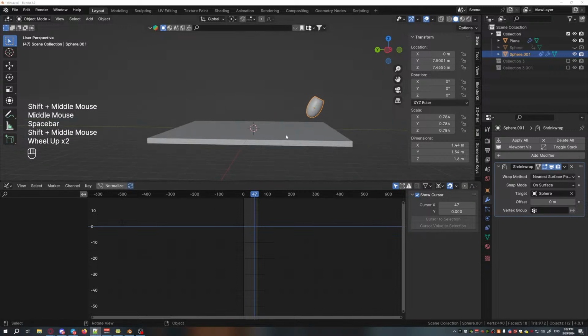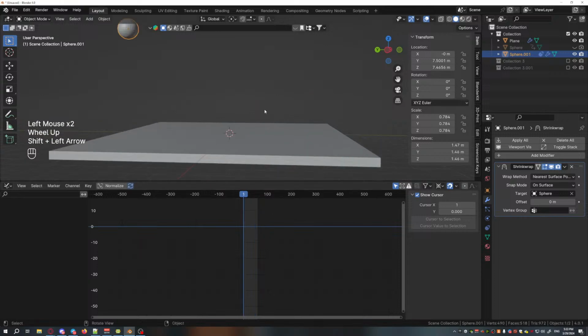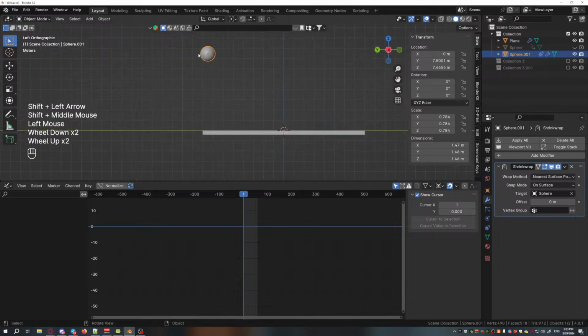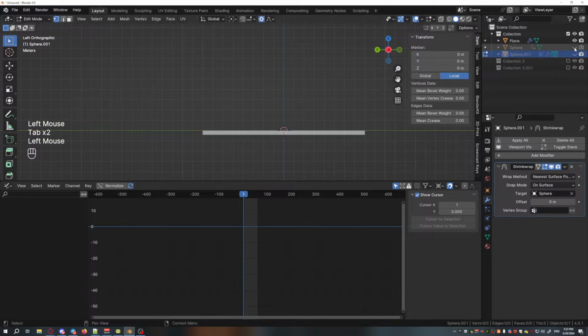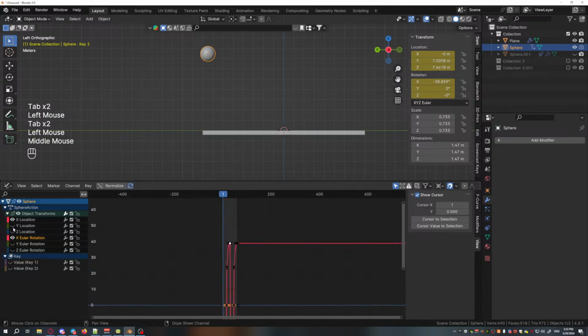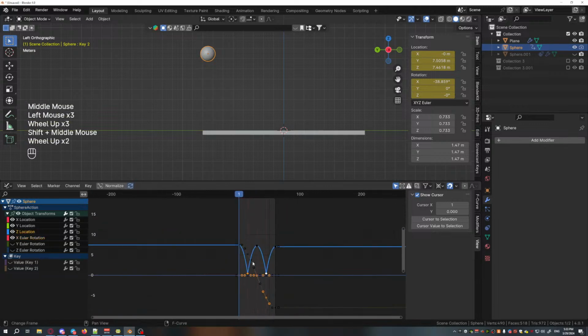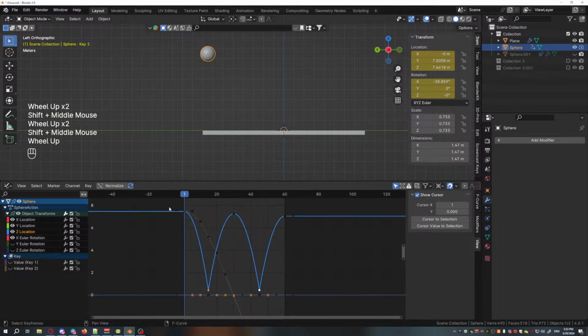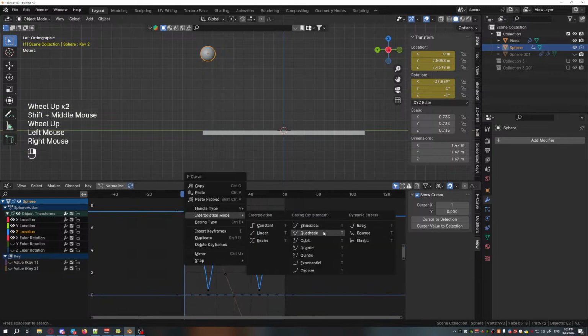We touched on how to make keyframes, how to make animations, how to open a graph editor, and how to change the interpolation types so that between our keyframes we have data change as we want it to change. Do you understand the logic behind the choice of the interpolation mode for the height of the ball? Why do we use quadratic easing?